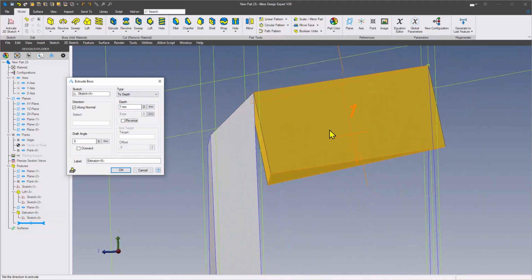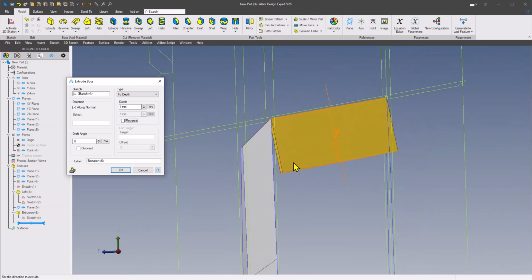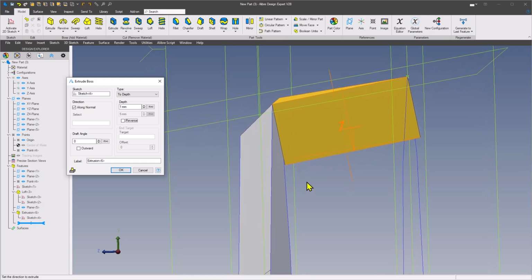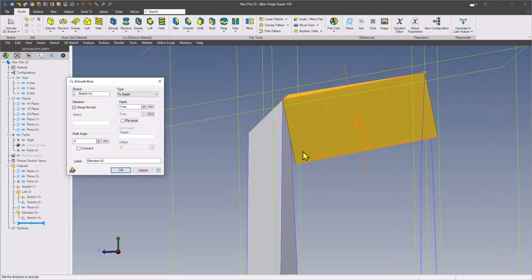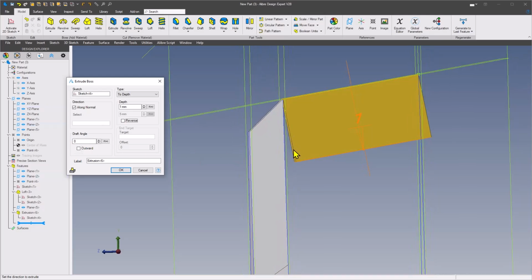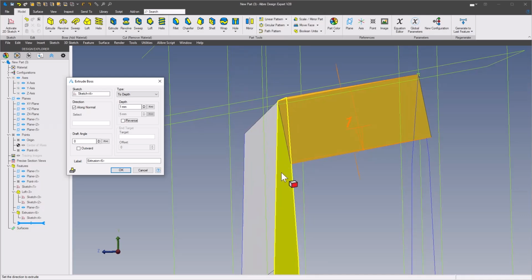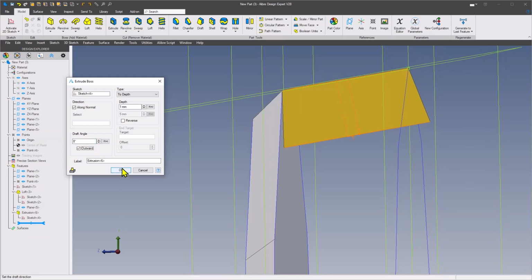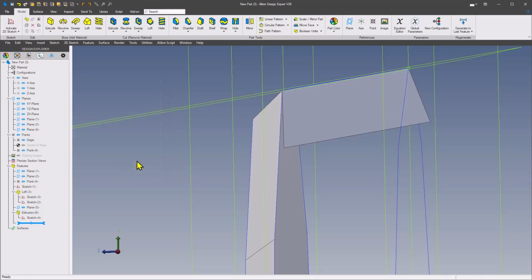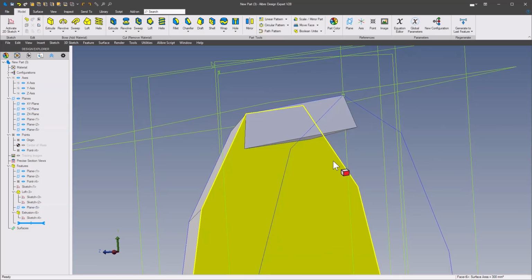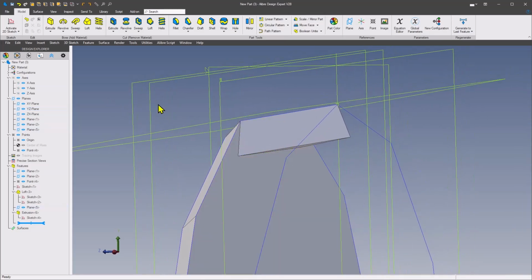And looking at this, since we're coming off this plane at an angle, we want to make sure that we don't have any voids inside the ring, which could cause problems. So we'll just add some draft to this so that we bring this face of this extrusion down into the body of the loft. So let's see if 8 is going to be a large enough angle, and if we click on the face there, we can see that the whole outside perimeter is highlighted.